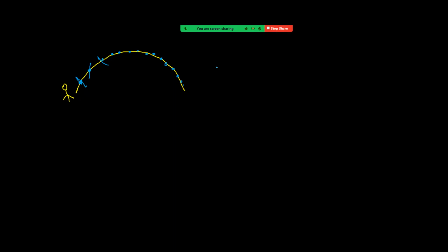If you remember earlier, if a block is moving, we have taken the block as a point mass. The reason was that when a block has translatory motion, each and every point has the same displacement, same velocity, same acceleration. That's why we have replaced the body with a point, and that point is nothing but center of mass. So we can assume the entire mass at its center, meaning at center of mass, and we can assume all forces are acting at center of mass.